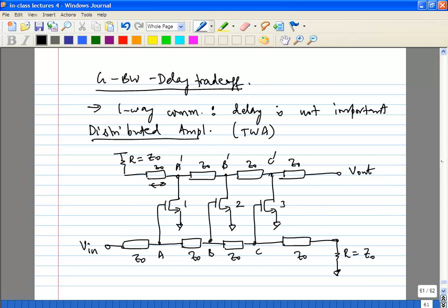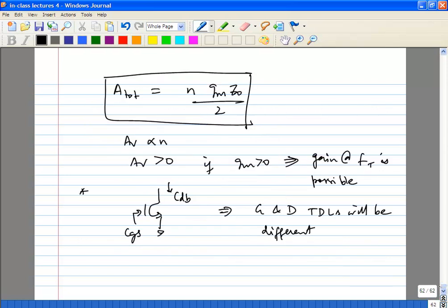you want a certain amount of delay. So that's what you want. You want equal amounts of delay. If you use lumped LC quantities, they actually give you enough delay that you need at the frequencies of interest. So you can actually use lumped LC for these transmission lines. Not models, lumped LC sections.